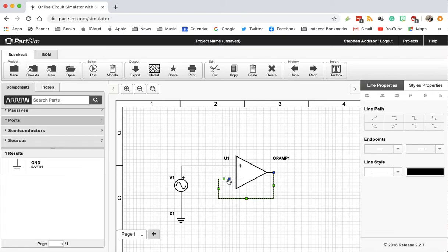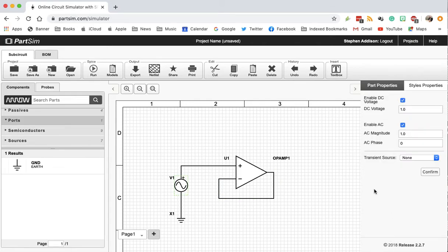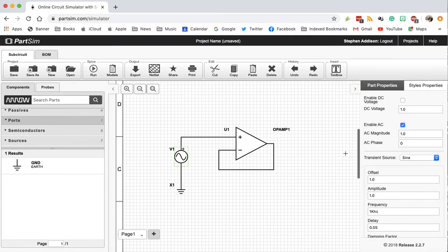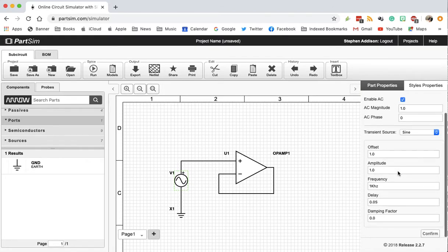All we have now left to do is to put a waveform in there in our voltage source. So let's bring that option up. So again, I'll use a sinusoidal source. So let's find it. Here's the sine. We'll stick with the defaults. I don't want a DC component, so I'll take that out. And then the step that's often forgotten, I'll confirm these choices.